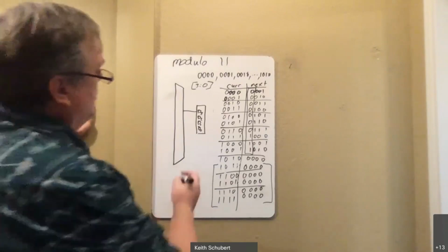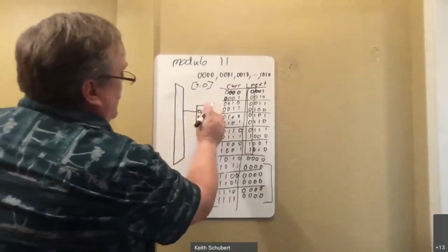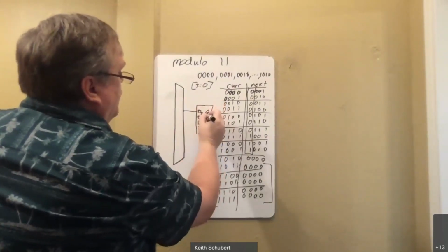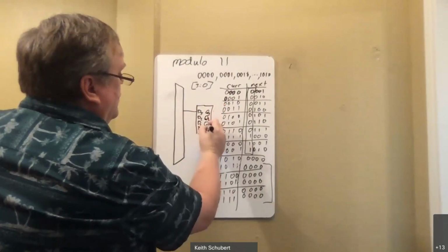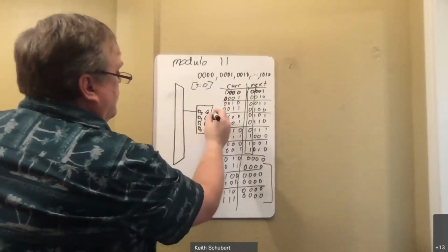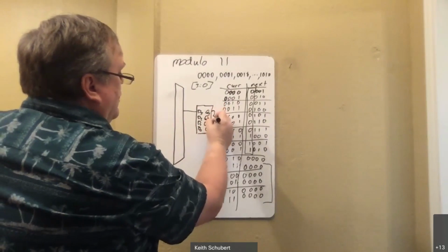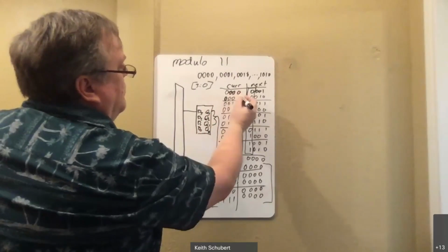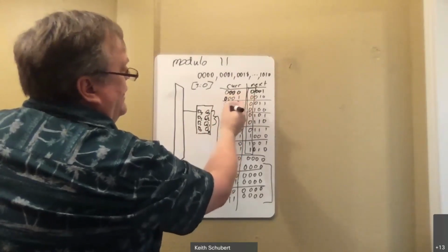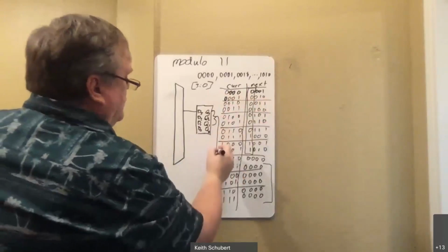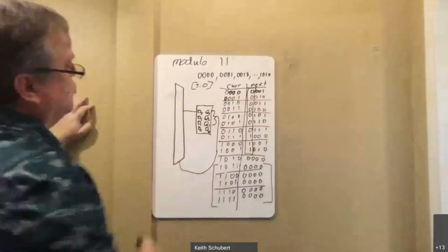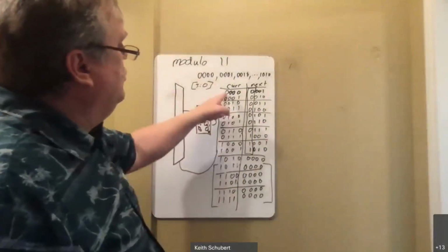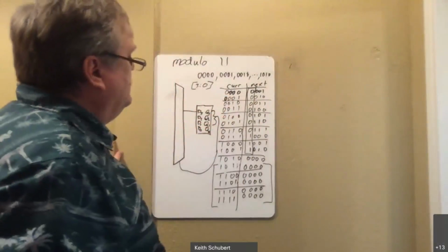Okay. So mux design, the output of this, I'm doing this a little bigger. I have Q3, Q2, Q1, Q0. The most significant 3 bits, that's these, are the same for any of these blocked out sections. That becomes the controller for all of my muxes. Every one of my muxes is going to use those most significant bits.